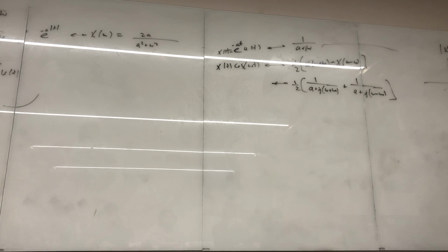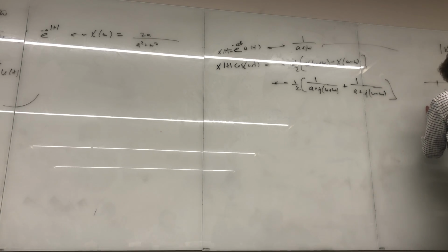And what happens? Well, it's got to roll off. It's going to be flat for a while, but whenever omega is about a, then it starts falling off as 1 over the square root of 2. And that's what you normally do, is you put a point on the omega axis, the value a, and then it will start rolling off like this.